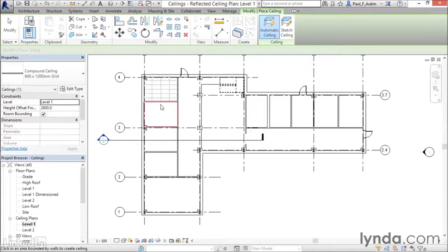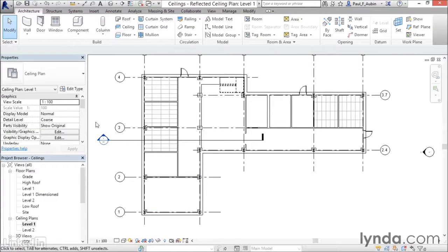I've got an office here, here, and here. I've got 2 over here. And then this one here is slightly problematic, as you can see, because when I highlight the boundary, it's actually flowing down into the conference space as well. So don't click that one just yet. What I'm going to do is cancel with the modify tool. And the solution to that problem is quite simple. This wall right here stops at the column instead of going all the way to this wall.